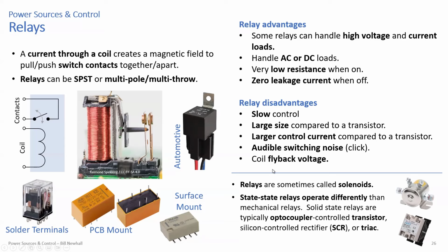Okay. Someone asks in the chat, would a bounce be considered a relay disadvantage? Absolutely. So when we talk about switches in the Intro to Circuits class, switches and relay contacts are what I like to call scratchy devices, right? They're rough. Those contacts on a microscopic level are rough. So when they push together, they hit, they slide, and that causes, on a very zoomed in level, connects and disconnects often